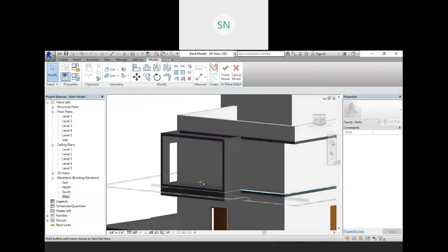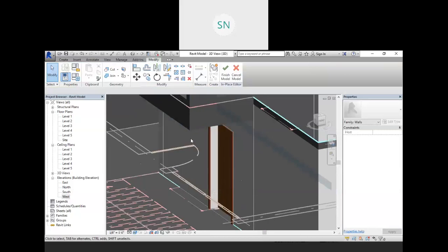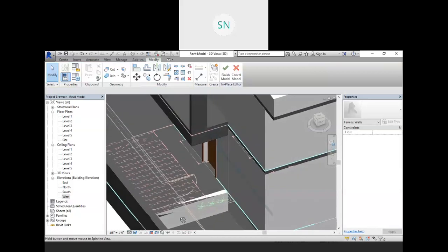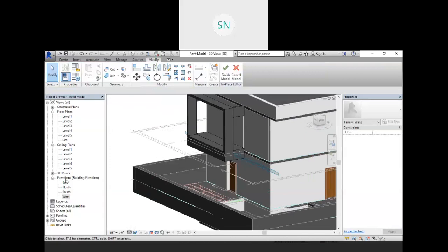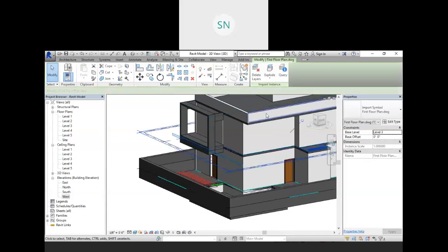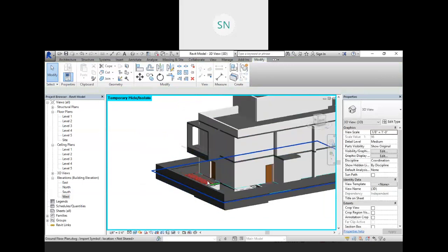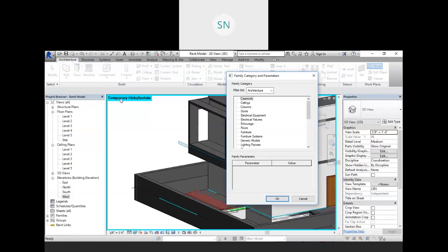Okay, so this thing we have done on the top elevation. Then from the bottom position of this line we have this thing with the 6 inches. So that sketch we have. So first of all we will go to level 1, or we can work from the 3D view also. Just finish this, select it and click on hide. Now just set your plane first, go to the architecture, click on the component model in place. This time it will be our floor component.